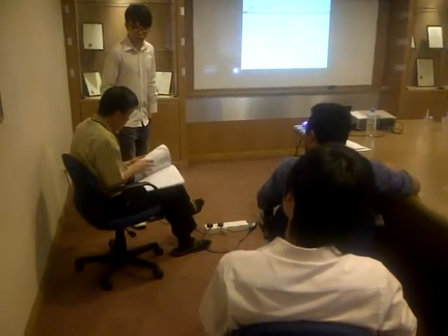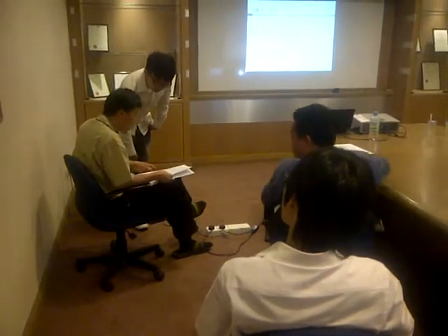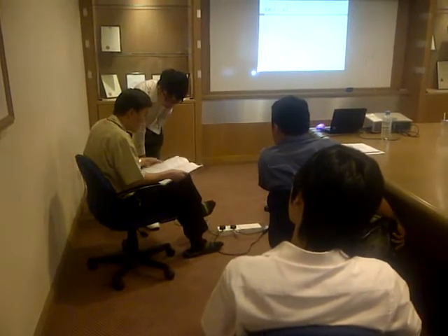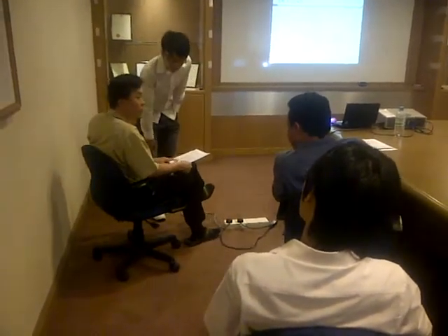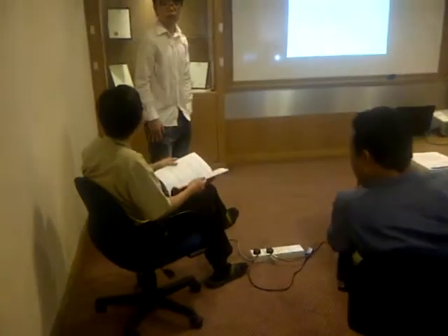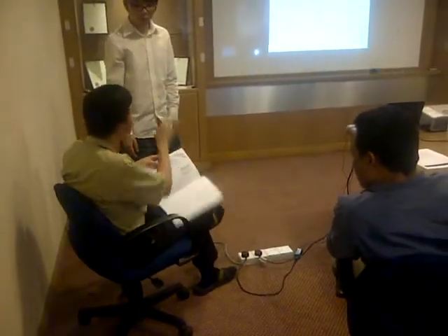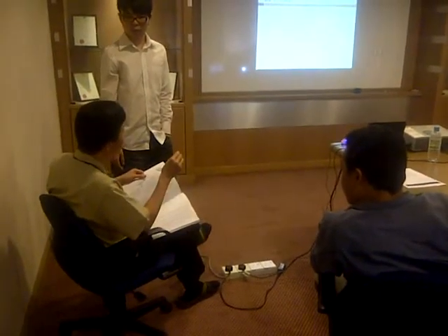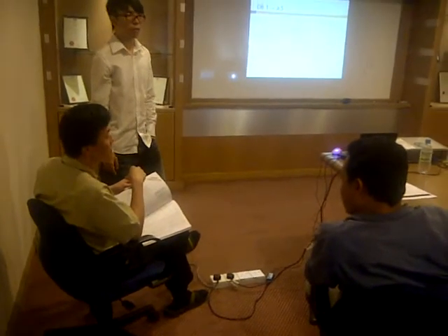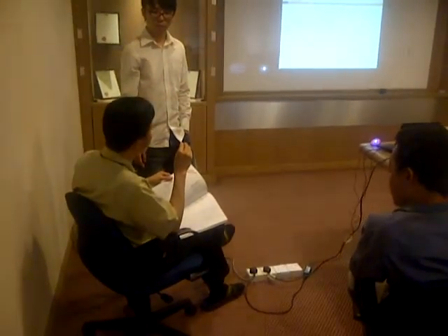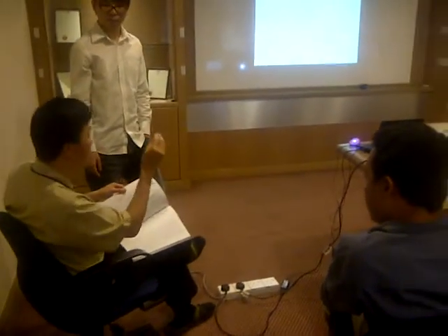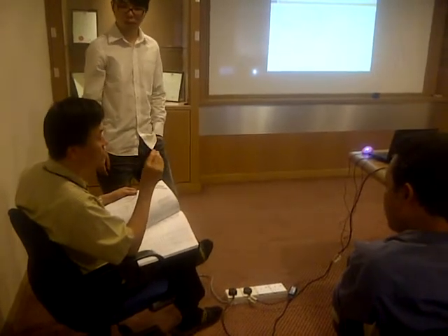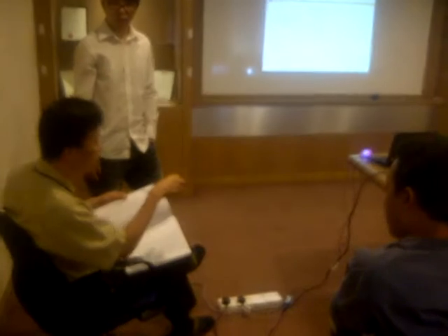There's one table here that's talking about temperature, the correction factor for ambient temperature. You have to give a derating factor already. Or else everything is based on perfect condition. But when you install at the site, you will find that your cable overheated, and sometimes the performance is not as good and certain things will intermittently trip. A lot of times things intermittently trip for the RCD because the whole system, the cable, is heated up.